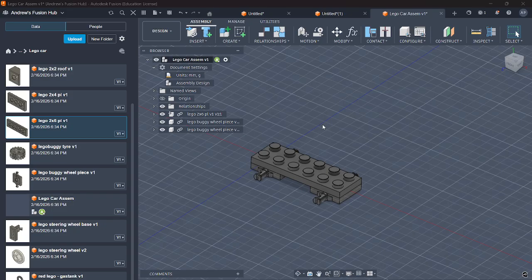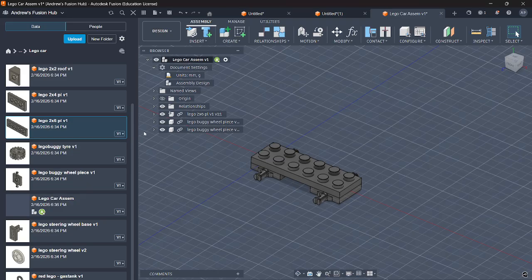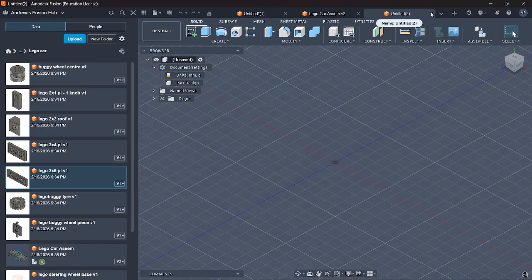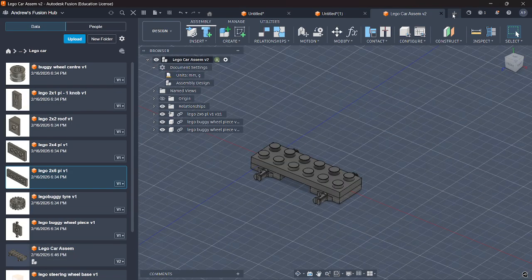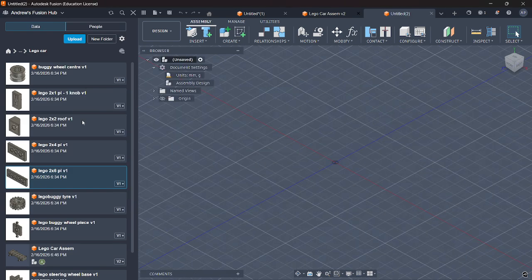And it's especially nice when you have duplicates of the same assembly. In this case, right, there's 4 wheels and tires. So we can create a sub-assembly that has both of them in it. So we don't need to make a bunch of extra constraints. We can just do it once and then place it where we need it to be. So, I'm going to create a new assembly.